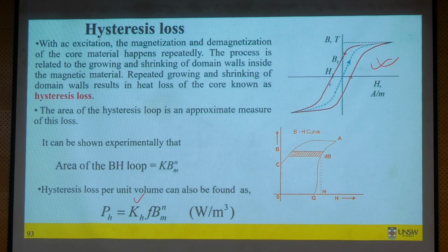So one of the biggest issues is that after like 200 years of electric machines history, we are still unable to accurately measure iron loss, or accurately estimate iron loss. You can do that for the no load condition, but in the load condition, this loss will change, because there will be saturation, there will be leakage. So we don't account for them when we do the no load test. That's why even now we cannot accurately estimate or measure iron loss.